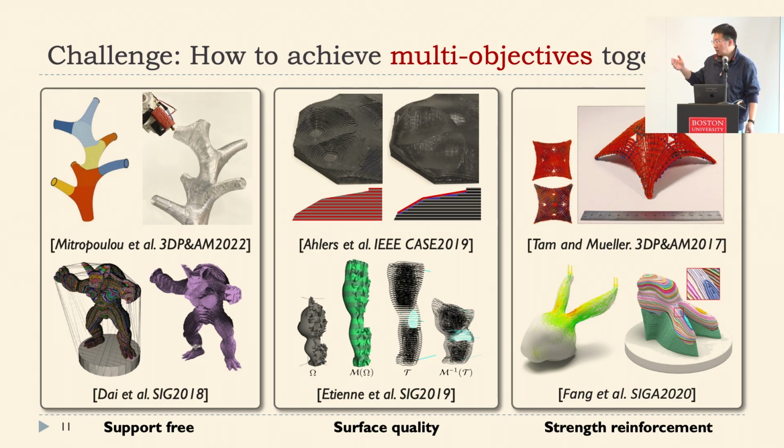If you're looking at 3D printing, one of the major problems of surface quality is that if you have a slope which is slightly tilted, you get many of those staircase effects, which are easily observed on the surface. So it turns out people are trying to align those final layers, either completely following the covering surface, or making them completely perpendicular to the surface which you are trying to produce. And not to mention the maximum stress direction and so on and so forth, okay?